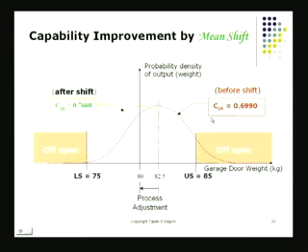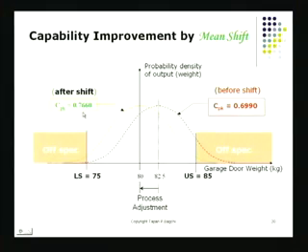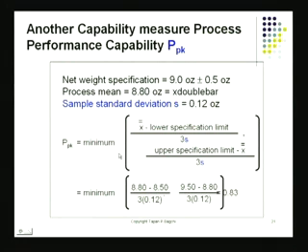and again process capability will improve. The old process capability with the off-centered process was 0.699, and the new process with your x double bar shifted to coincide with what we call the target value, that CPK turns out to be 0.766, which is larger than 0.699. Therefore, there has been an improvement in the process. And this improvement we have achieved by shifting the mean of the process. The red curve was shifted to this yellowish curve there. And that's how you end up improving the process.